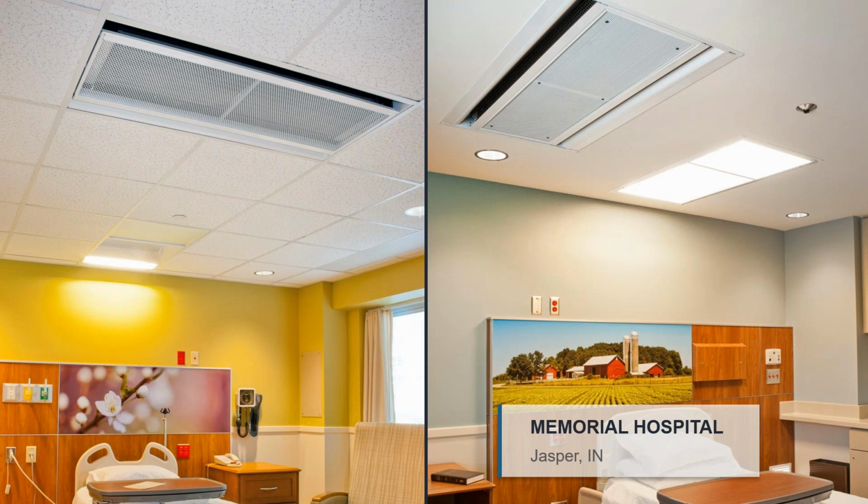You can also notice that the perf spacing is a lot tighter on that, and that is by design. That's to meet various local codes and even Title 24 on the perf spacing, and even down to the diameter of it, for various reasons and for protecting the patients themselves. But there's also, some of you might be able to see, a perf even up within the slot diffuser to keep anybody from being able to get up there and mess with that or run string through it, to provide the maximal security within the unit.